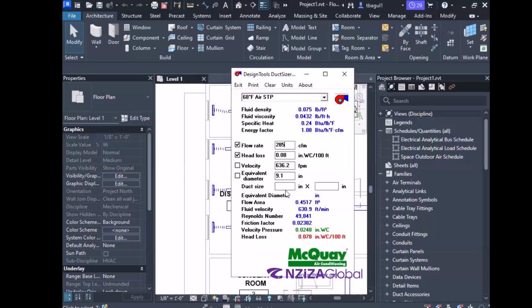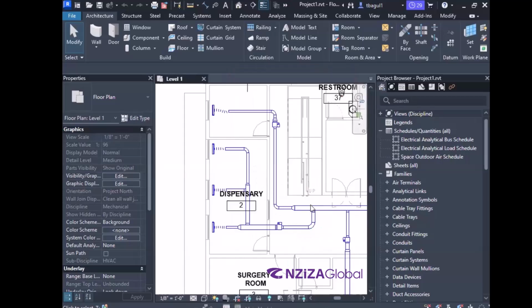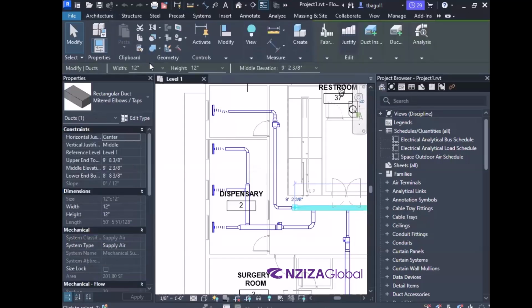For checking how we can use a square duct size here, okay? What duct size do you think can work with it? So now once I put 8 over here, the software automatically detected 9 inches. Just a minute. But again, as I said, the ducts are usually available in even inches or even mm as well, right? So over here, it will become a 10 inch. So this duct of mine needs to be a minimum of 10 inch by 8 inch.